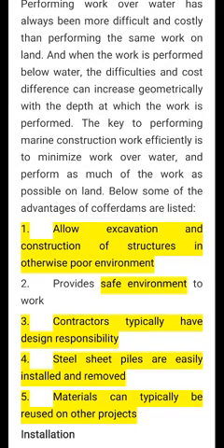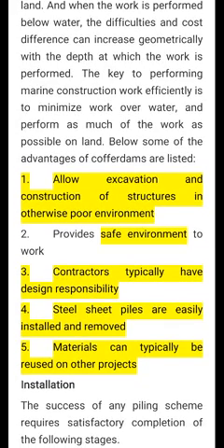Contractors typically have design responsibility, not the client. Steel sheet piles are easily installed and removed. Material can typically be reused on other projects. As we have discussed, it is only a temporary structure, so we can reuse it.